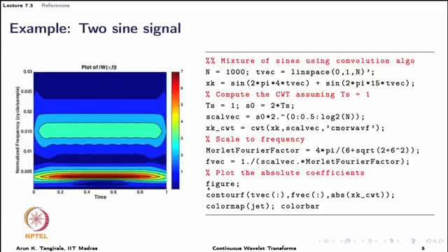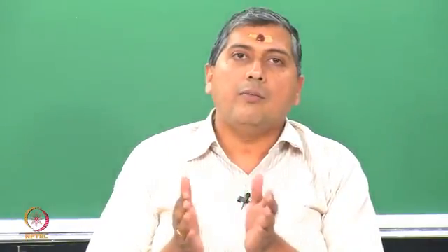And then what I do is I draw a contour plot of the magnitude of CWT with time on the x axis and frequency on the y axis, and the magnitude plot clearly brings out the presence of 2 frequencies. Now, observe one thing that you should expect: the wavelets will give you more smearing of the energy at higher frequencies, because they are highly localized in time, and by virtue of the duration bandwidth principle you should expect more smearing of the energy in high frequencies.